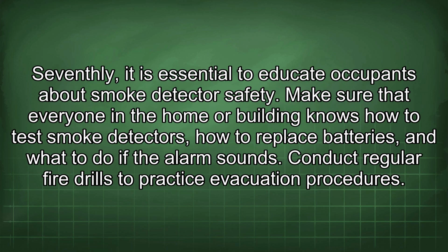Seventhly, it is essential to educate occupants about smoke detector safety. Make sure that everyone in the home or building knows how to test smoke detectors, how to replace batteries, and what to do if the alarm sounds. Conduct regular fire drills to practice evacuation procedures.